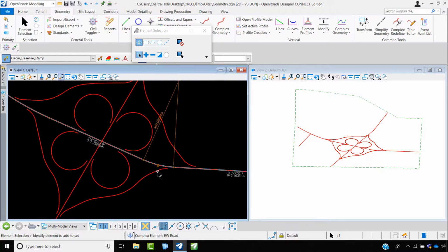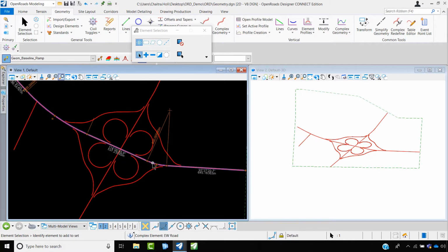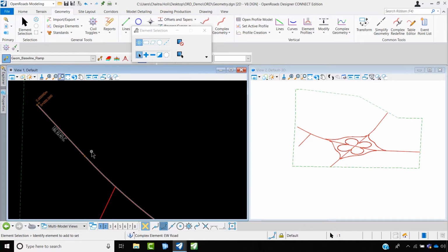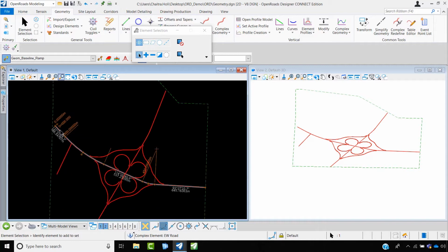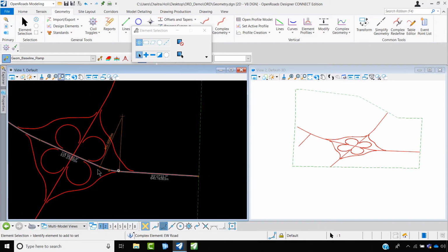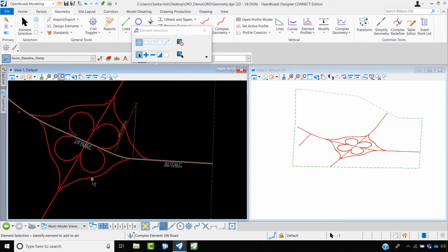you see these manipulators, text manipulators being shown over here depending upon what type of element you're choosing. Over here it shows me the zero chainage where it starts, 500 meters. You could see the radius over here, so it shows me all the text the moment you click on any of the element. So let's move ahead in order to edit my horizontal design.